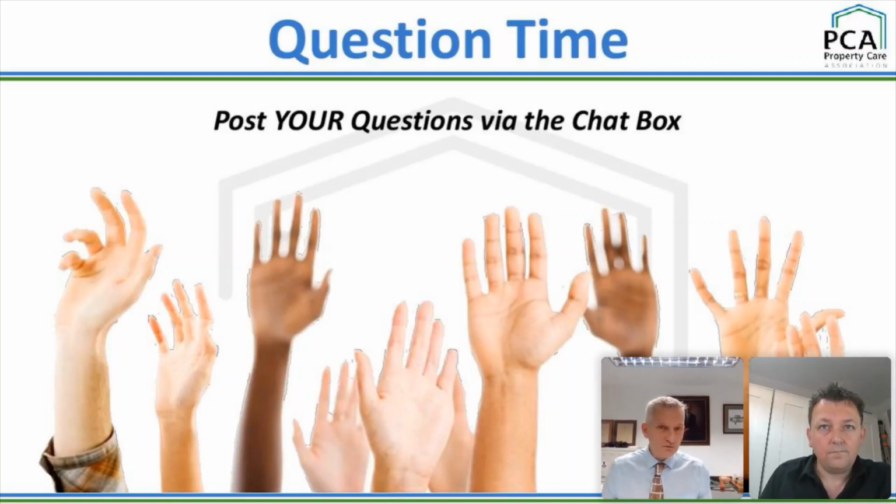But if there's an underlying reason why the walls are being pulled to and fro or settling up and down, I defer to structural engineers at anything below DPC level, you know. But basically, if that sort of thing's happening, then all you're going to do is shift it to another area, you know. So it's important that you get advice, that somebody looks at it and says, yeah, I'm happy, let's repoint it and look at it next year.